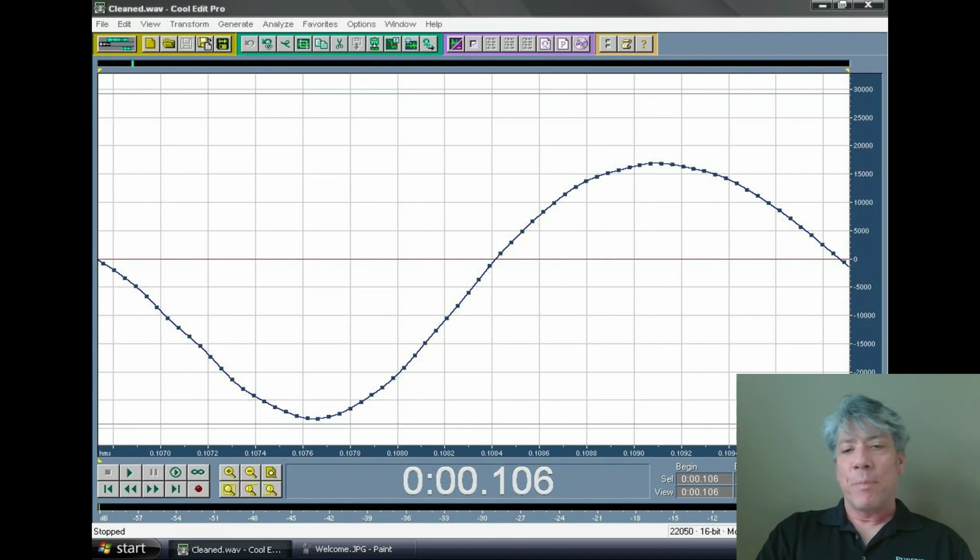But anyway, the 16-bit means there are 16 bits associated with each sample to record that sample. With 16 bits you can record 0 to 65535. So that's 65,536 different positions, including the neutral position, or the zero position in the extents. And so remember I was talking about the microphone's diaphragm's position being discretized. Well, it's discretized into 65,536 different positions, which is pretty doggone good resolution. It's not bad at all.